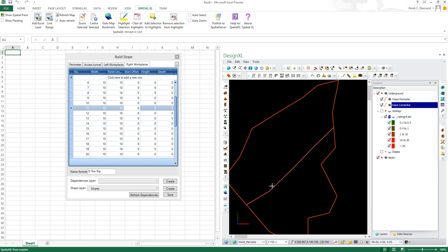So I'm in the center line plane. I'm going to choose to extend the center line, and I'm going to insert a vertex after to extend it, and I'm going to move it up to about there. So I've extended the center line.